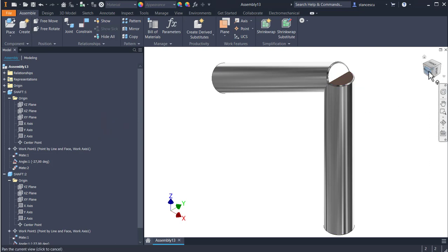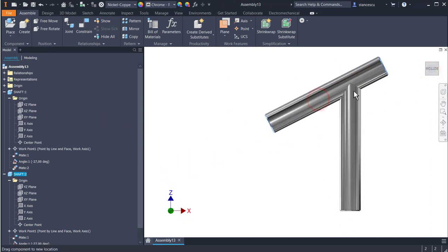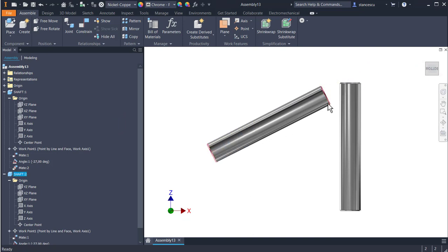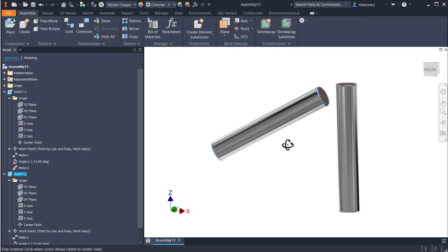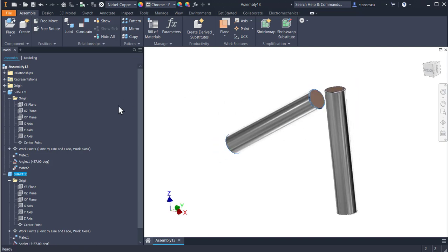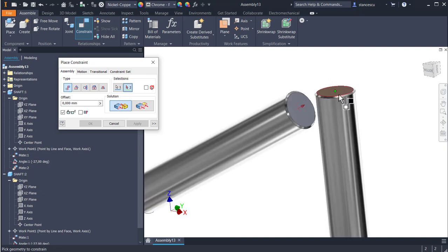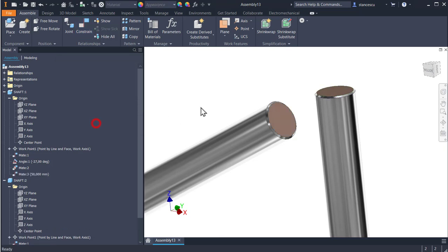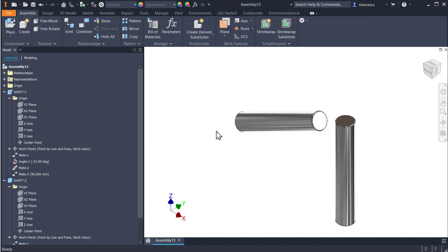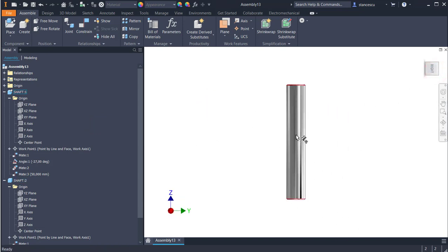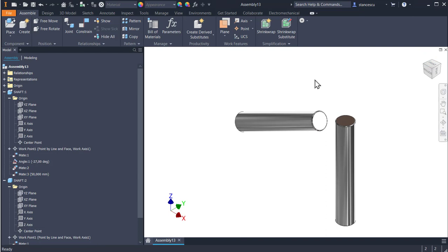What do we have here? We have this situation. We can move the second shaft only along its axis. We constrain this face to be at a distance from the center of 50. Okay, F6. This is the starting situation. You see they are coplanar. The two are coplanar. This is the condition for the bevel gears.